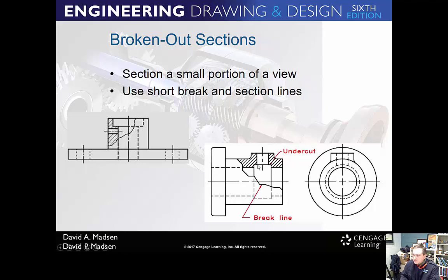This one's the same idea. They want to show this undercut, and again, on dimensioning, I'm kind of baffled why you wouldn't want to have this fully shown here. Break it all the way down so that I could see this and dimension both this and get a diameter on it. But again, you could take the dimension here and do that. It would also be possible, I don't know that it's actually wrong, that you had a leader and pointed to it and said, hey, it's this diameter. It's just an alternate way of thinking about dimensioning.